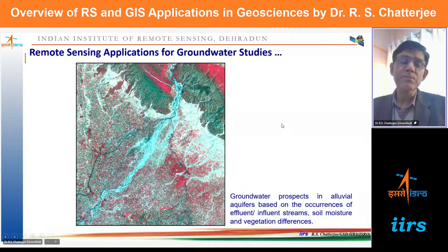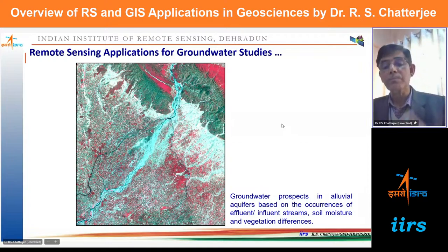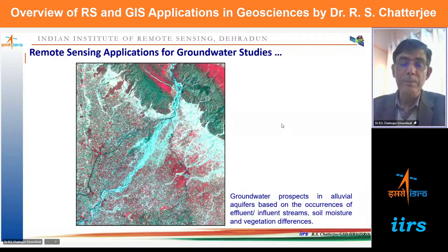So just from the image itself, you can have some kind of assessment of where groundwater is available or not. Now you can do a lot of studies by integrating different factors. Different kinds of observations are required, different geological, geomorphological variables we need to integrate together, and then groundwater level information which is available from the Central Groundwater Board and the state boards. Okay, and the rainfall and other information. If we integrate together, we can have much more robust information about the groundwater availability.